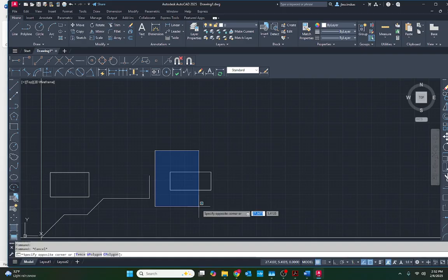And the reason I essentially finished that is that this unit, this device, is actually a box. So when I move this, I can move the whole box. When you draw lines, the lines themselves are not connected together. So if I click on a line, I select only the segment.